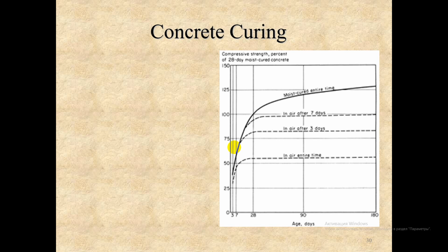The finer grains and different raw material used in this cement enable water to access a larger surface area of cement and so react more quickly than if a coarser grain cement with different constituents, like OPC, were used.